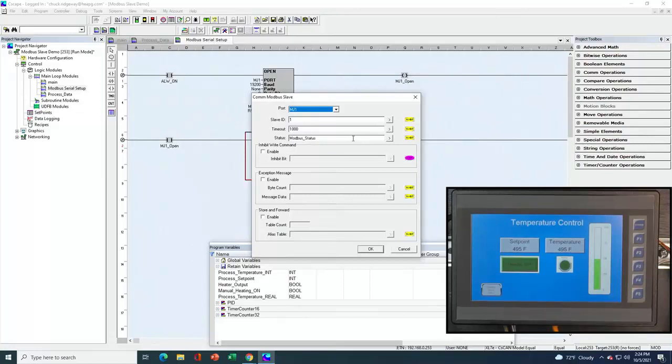And again, it's important when you're doing communications to take advantage of status. Now down here, next, you'll see we do also have an additional variable that's optional. So if we want to be able to use a bit type variable to, on the fly or even permanently, prevent the OCS from being written to. So in other words, you want to be able to provide access for Modbus for reading, but not for writing. If that was the case, you would enable this variable here and you'd create or assign a variable to prevent the OCS from being written to.